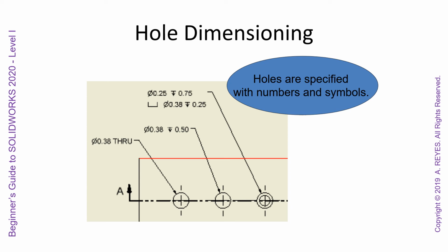This hole will just be a diameter of 0.38 with a depth of 0.5, and this hole will be a diameter of 0.38 all the way through the part.